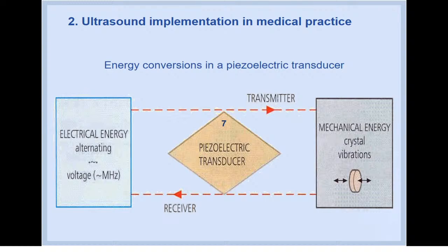The ultrasound generator basically consists of a sine oscillator and a transducer. The sine oscillator generates high frequency, more than 20,000 Hertz, electric power, while the transducer unit converts the electric oscillations into mechanical ones.